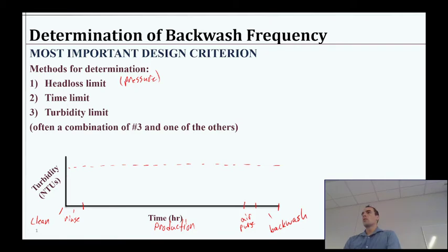So with a clean filter we talked about last time, essentially what's gonna happen when we first start pouring water through it is we're gonna have some debris come out. Whether it's because we just backwashed it and there's some particles still stuck in there ready to come out as soon as we push water through and the sand grains settle into place again, or maybe it's a brand new filter and we just have specks of carbon coming out, right? Like we put in a new Brita filter, we want to pour a couple gallons of water through it, get all the little black specks you don't want to drink. Probably be okay, but you just don't want to because it looks gross, right?